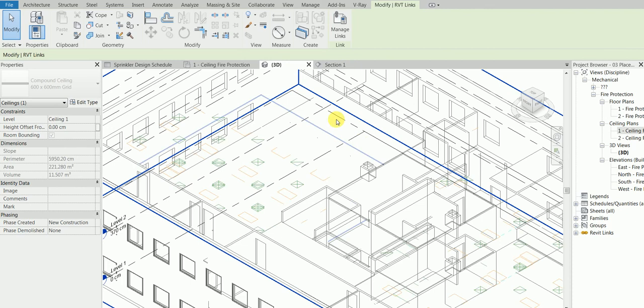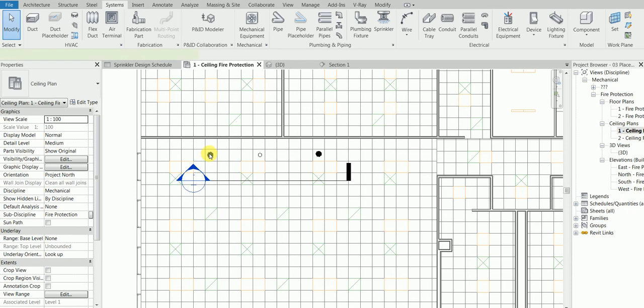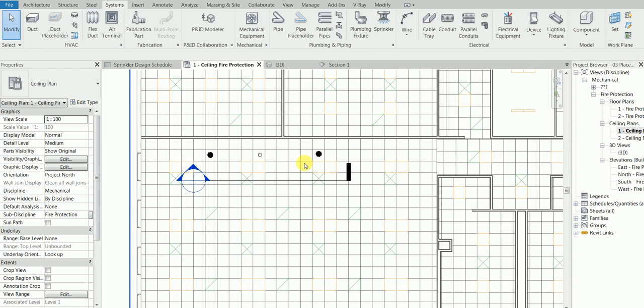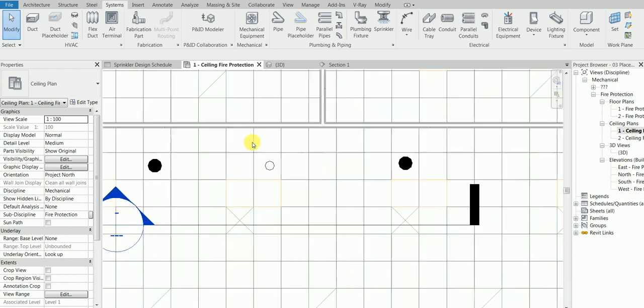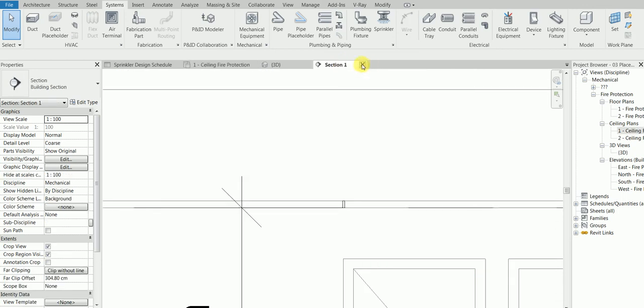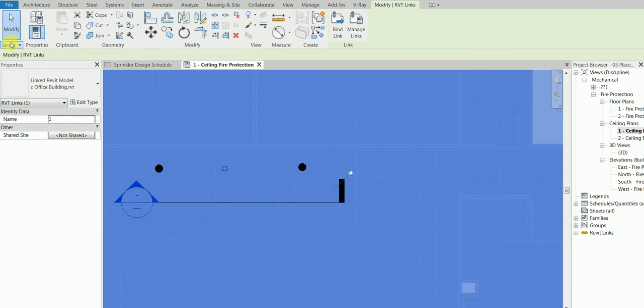Consider this is the trailer for that movie. So in the next class I teach you what's the difference between hosted and non-hosted family. Okay, and yeah, one minute, 260. Don't keep typing the wrong number. What's the difference between hosted and non-hosted, and how do we know the elevation of a given object? If I want to know the elevation of this point, what's the elevation? If I want to know the elevation of this, how to do it without going to the section view? Let's just close this, isn't it? I hope it's clear. We should not have selected that bit.